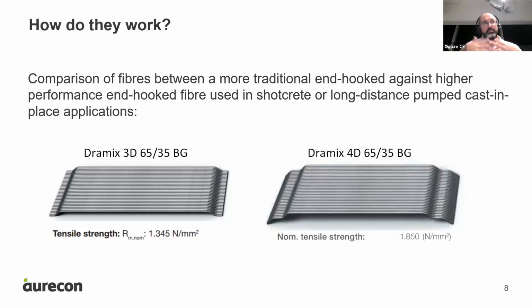Concrete strength for durability, at least here in our practice in Australia, is that we don't use anything that's less than 40 MPa concrete. Right? And when we're looking at a 40 MPa concrete, there was a significant benefit when we started migrating from this lower strength fiber to these higher performance fibers with higher capacity, where we could mobilize a lot more flexural capacity